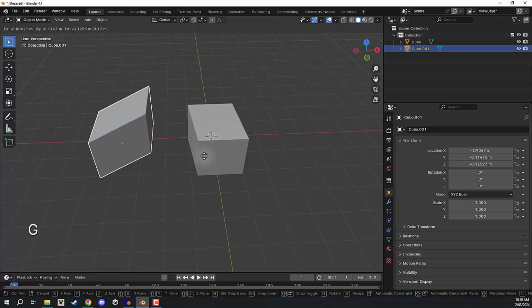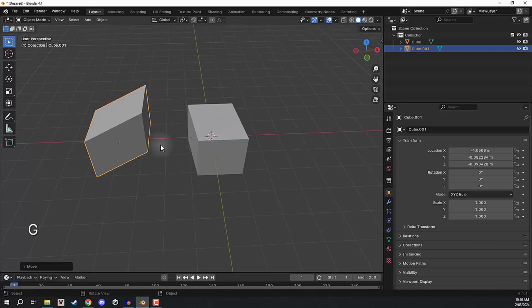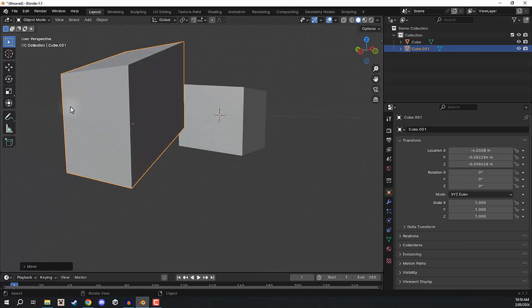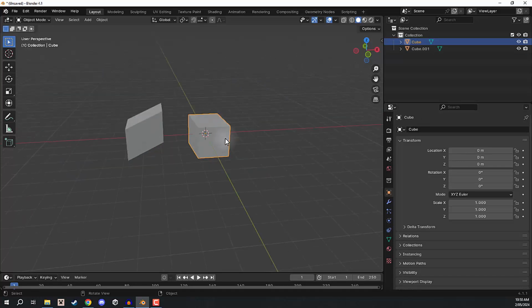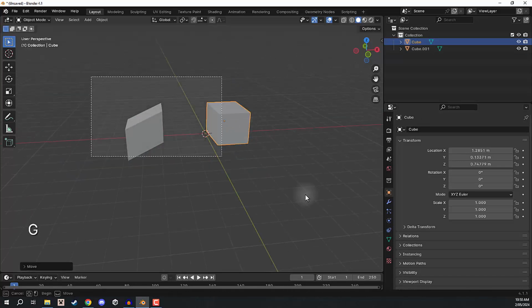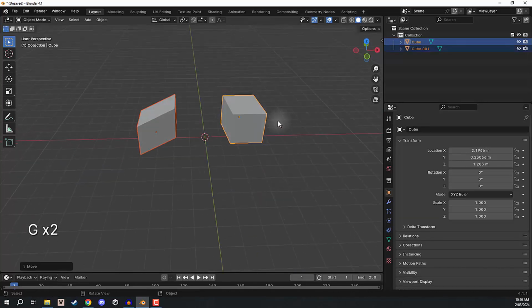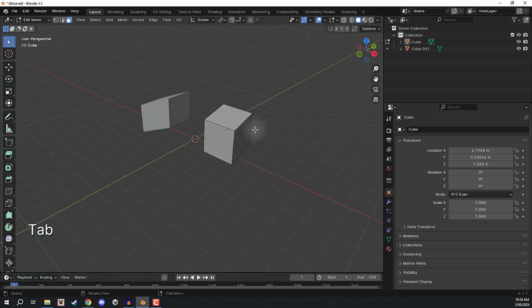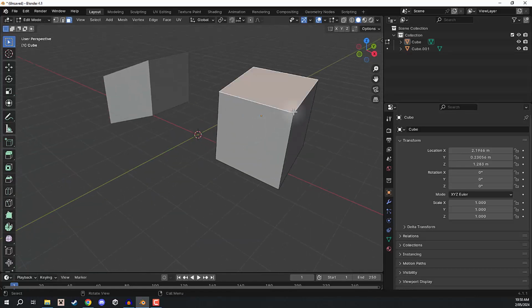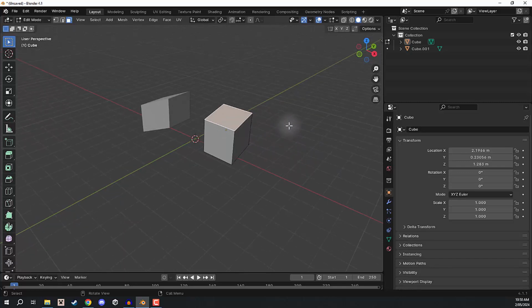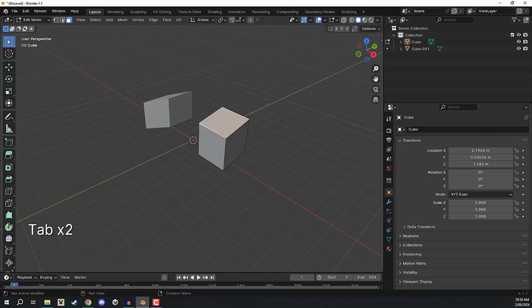We can select objects, we can move them around, we can rotate them, scale them, but we can't really edit its individual aspects. But we do have the ability to modify multiple objects at once, like so. Whereas edit mode is where we start going into the finer details of a specific model, okay? So yeah, that is a look at edit mode inside of Blender.